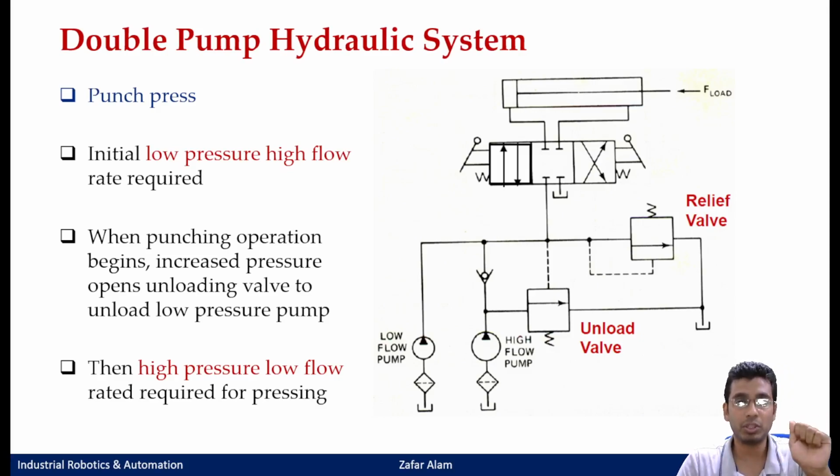the lever back, you have not disengaged your extending position of your DCV. So what would happen? Since this is a high pressure pump, it would start building up the pressure beyond 150, because till when the cylinder was moving, 150 was the operating pressure. The moment the cylinder got completely extended, there is no movement that can take place. So what happens here? Pressure starts to build.